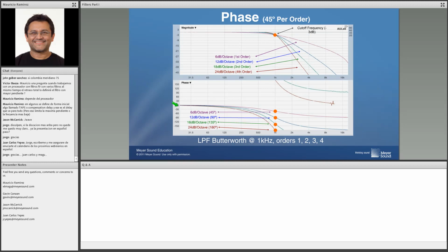In the phase display, what we will have is not milliseconds, it's not decibels, but it's called degree. And the phase display will be, for any given frequency, 360 degree. So this means from the top to the bottom is 360 degree at any frequency. 360 degree, it is the same as one cycle, or the same as one time period, or the same as one wavelength. So if I am here in the position 0 degree, you can see that going in this direction, reach 180 in this direction, and reach the other 180 in the other direction. So the deviation from 180 to the opposite 180 is 360 degree.